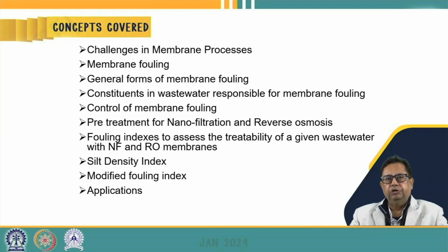In this lecture, we will cover the challenges in the membrane processes, the membrane fouling process, what are the general forms of membrane fouling that happen when we are treating water or wastewater by using the membrane processes, the constituents in the wastewater which are responsible for the membrane fouling process, how we can control the membrane fouling process, and what pre-treatment we require when we are using nano-filtration or reverse osmosis process for the treatment of water or wastewater.